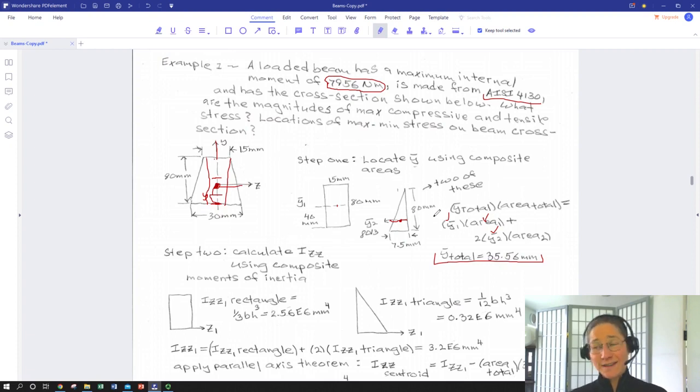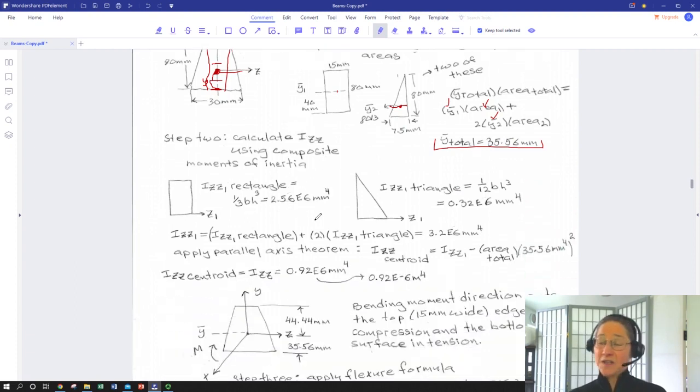So having calculated that, then we need our Izz, our moment of inertia. We can use some tables. There's probably some tables in the back of just about any textbook you might be using. If you're using a table of moments of inertia, in most cases, different values will be listed for an axis through the centroid versus an axis across the base. And if it's not a totally symmetric type of shape, there'll be a different moment for rotation along different axes. And then a polar was, of course, the sum of the two orthogonals.